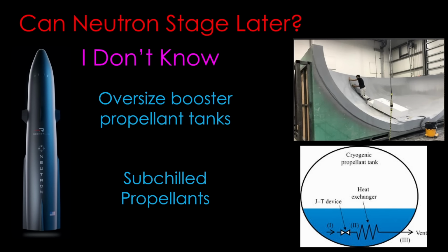per flight, though it would likely require some new molds for the second stage, and the cost savings probably aren't great. I expect that they would use higher booster performance for the traditional use, which is to increase payload to orbit. That will be more valuable than a slight reduction in second stage cost. There is a partially reusable rocket that plans to stage much later, and that's the second one to discuss. That rocket is ULA's Vulcan.